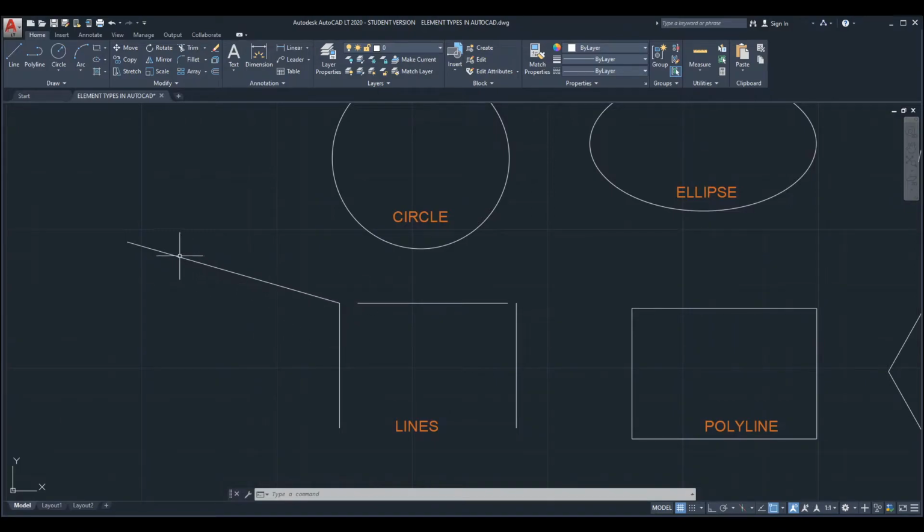So this is called snapping, where your geometry connects to another point or references another point, and AutoCAD highlights that specific point on the geometry. And that was regarding the endpoint. Let's look at the midpoint. I'm going to start another line here, and then I'm going to move closer to the middle of this line, and you will see we get a green triangle. And if you hold the cursor for a second, you will see it says that this point is the midpoint, and if you click in here, it will connect the new line to exactly the middle of the existing line we had originally here.